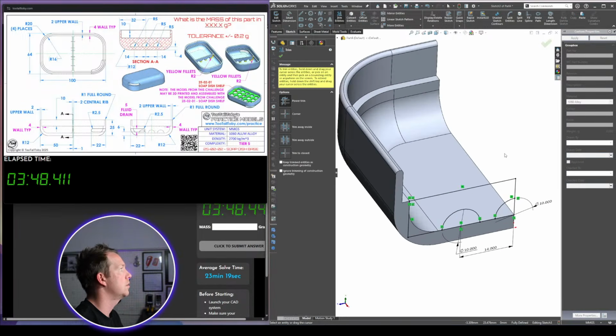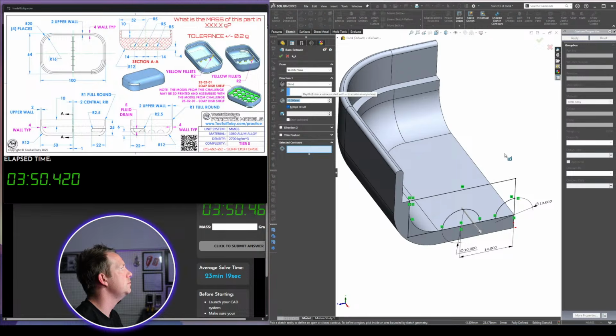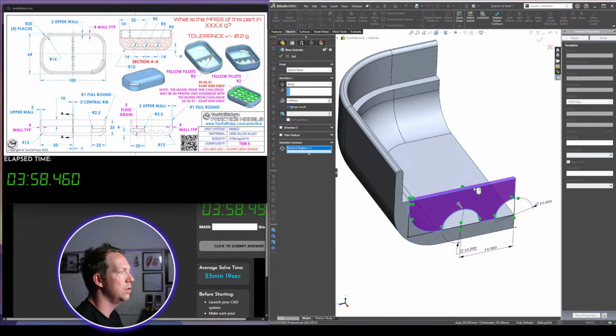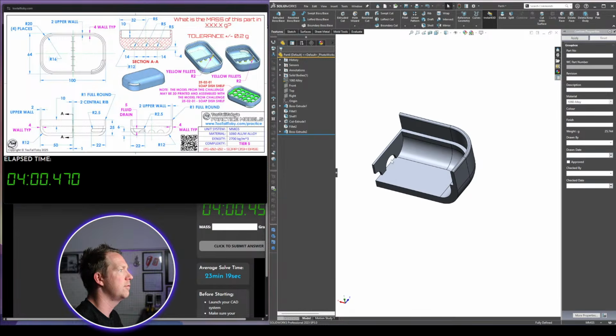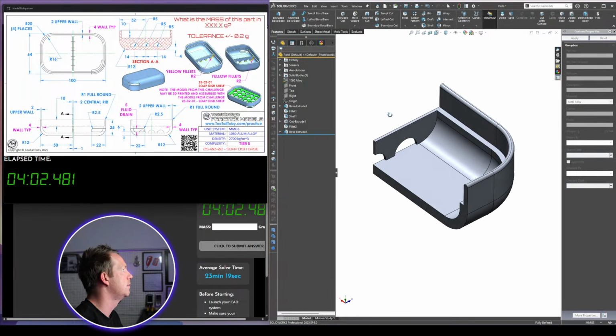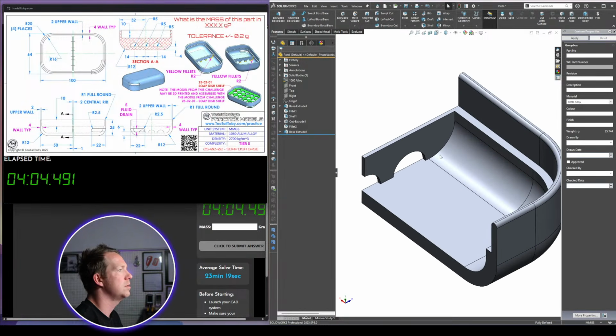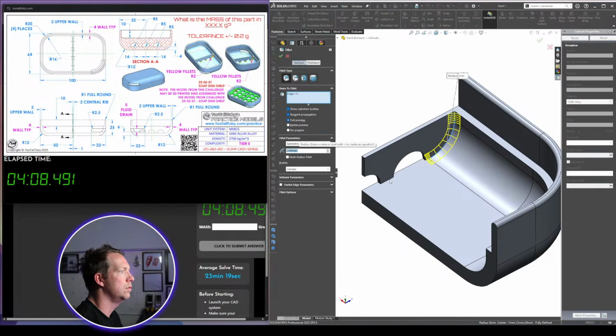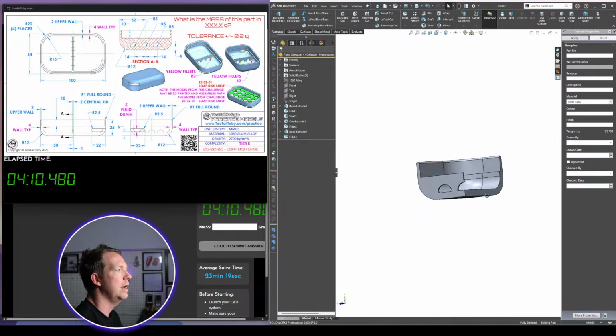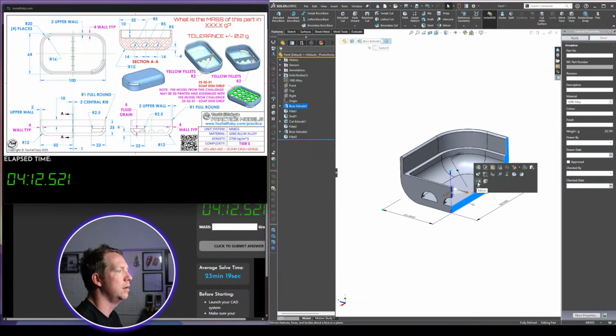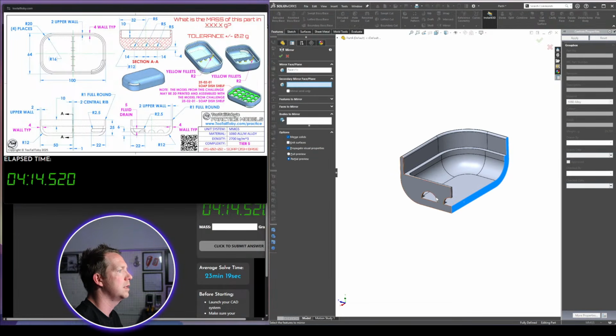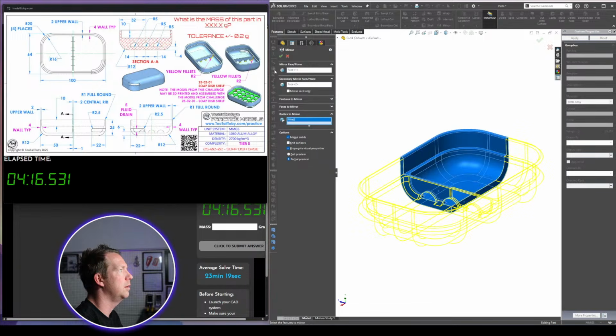Okay, so then I can extrude that. Now the total thickness of that section is 2, so if I go 1 millimeter in this direction and select that contour, that's going to be enough. I can put the fillets in here. That's going to save me some time, so it's got an R2 fillet. 2, 2. Alright, now we should be ready to do a double mirror. So I'm going to select these two planes, select this body, merge it.